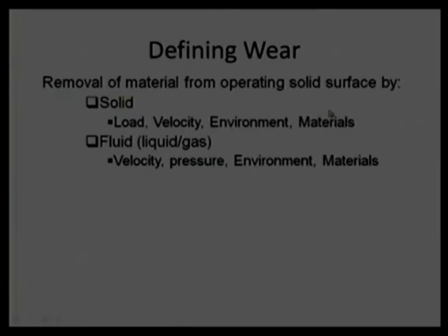If there is a good hardness of material or good compactness of material, then wear will be lesser. If the environment is friendly, wear will be lesser. A larger velocity by and large will cause more wear, except in the hydrodynamic domain, and high load will cause high wear, except in a few cases where low load may cause some vibration and larger load will avoid that vibration.